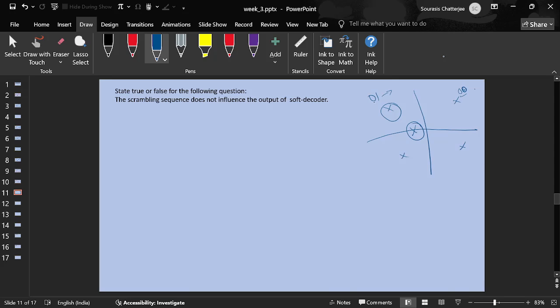So the receiver is confident about its decision, that even if 00 is transmitted, just because the noise corrupts the transmitted symbol, so that your received symbol is here, and you apply the nearest distance detection rule, and you obtain your transmitted symbol to be 01. So the receiver makes the decision from there onwards. This 01, even if it's incorrectly decoded, will go through the scrambler and then LDPC decoding.